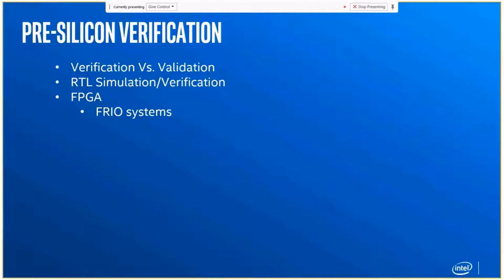But you can do a lot more testing on an FPGA system compared to what you can do with RTL simulation verification. Right? With RTL simulation verification, all you can do is write the bit, read, write. So it's really at that level. With that FPGA, you can connect a traffic generator. You can send traffic in. You can go circulate, come back. You can load the software that you are designing for the device. You can do all that. But still, if you want to mimic the entire device, you may need a room full of FPGAs to mimic one device, right? You usually don't do that because it's cost prohibitive. It's extremely expensive.